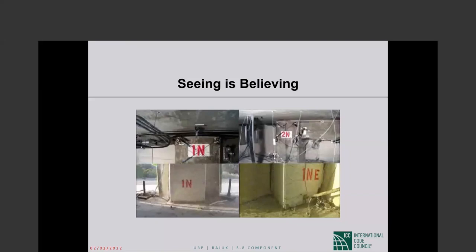Anyway, improving the site will be a much better bet before inserting or casting the piles, because you have seen in the case of liquefaction, piles do actually pull out. So if you don't want to take that risk, then improving the site will be a much better way to proceed.